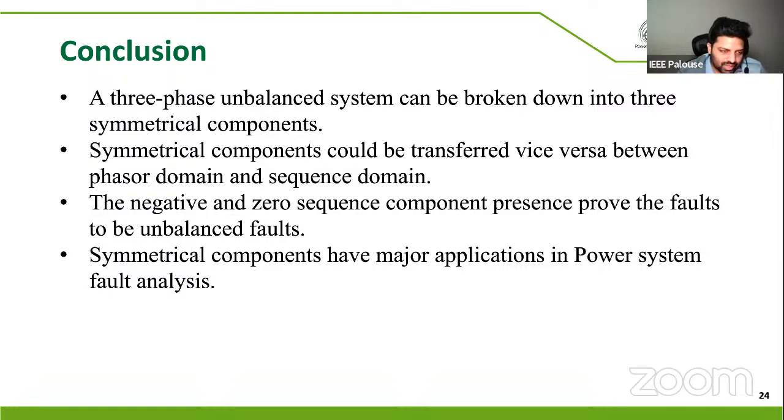Strictly speaking, you will never have an exactly balanced three-phase fault. You will have some imbalance within the power system with the loads themselves, so you will never have an ideal three-phase fault. But in theory, if you have a perfectly balanced three-phase fault, you'll have balanced fault currents flowing. So with that, we proved that the symmetrical components have major applications in power system fault analysis.